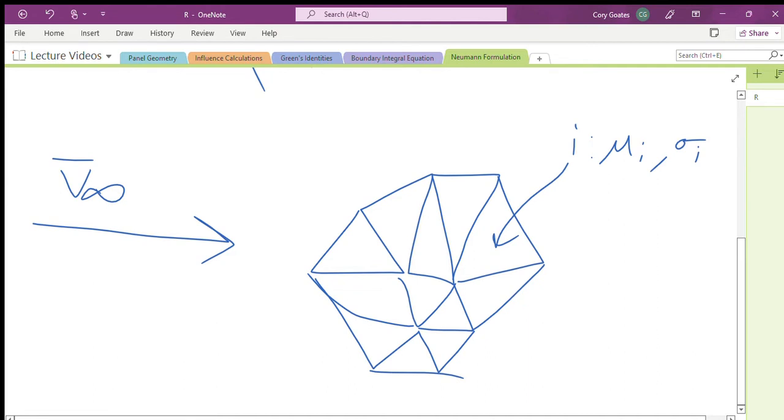Now, for now, we're only going to be looking at panel methods that have doublet strengths defined. These are called source-free or vorticity-based methods. Later on in this project, I'll explain how you can add sources. That's an extra credit portion of this. But this is one of the reasons it's really important to understand the basics of panel methods. If you know the basics, then you can understand when you can leave out sources and whatnot.